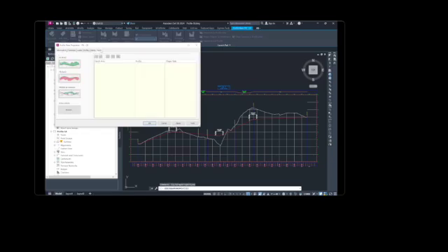We're going to define now a cut area hatch. On the hatch tab, select cut area. In the shape style column, click standard. And then in the pick shape style, select cut and click OK. In the profile view properties box, click apply. The specified shape style is displayed in the cut areas between the profiles.